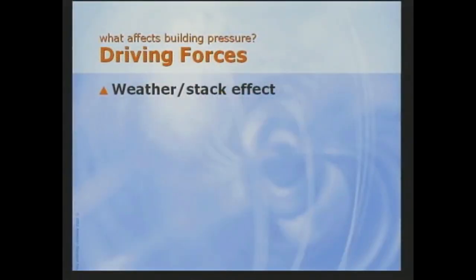So how much building pressure is needed to get the benefits of pressure control without the problems? Before we can answer this question, we need to understand what causes building pressure to change. There are usually only three driving forces that impact building pressure: the weather, the wind, and the operation of the HVAC system. Let's start with the weather. Whenever outdoor air is warmer or colder than indoor air, the resulting difference in density causes a pressure difference that varies with building height. This weather-dependent pressure difference is called stack effect.